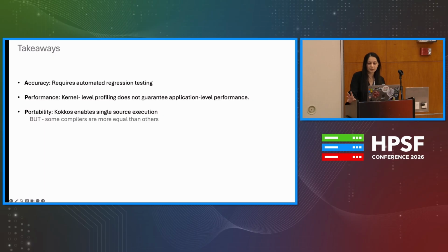I would like to add that for this work, we relied on unified memory and were careful enough to avoid correctness issues from incorrect view placement. But as we move to 3D Euler equations with much larger memory requirements, we are starting to notice silent performance hits. For example, silent fallbacks to host DRAM on HIP, and this is something we're actively investigating. Thank you.